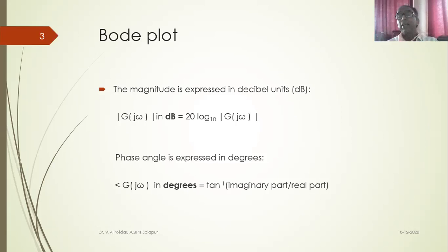Now, as a designer, working on paper with mathematical terms, if for given values of the transfer function, for a sinusoidal input, the system is tending to be unstable at particular parametric values, I can suggest changing these values of the parameters so that the system becomes stable. So this is the prediction of the system behavior based on Bode plots.